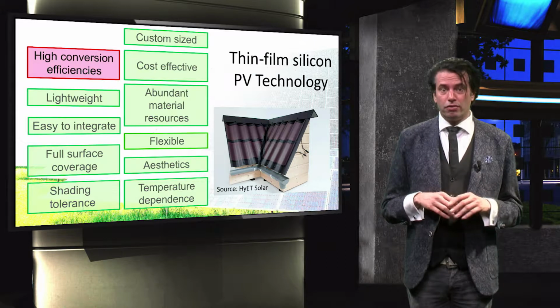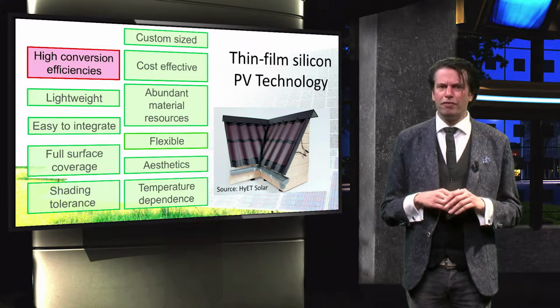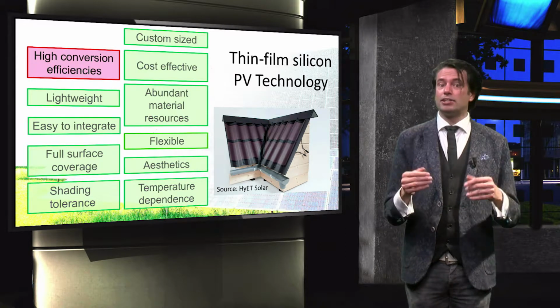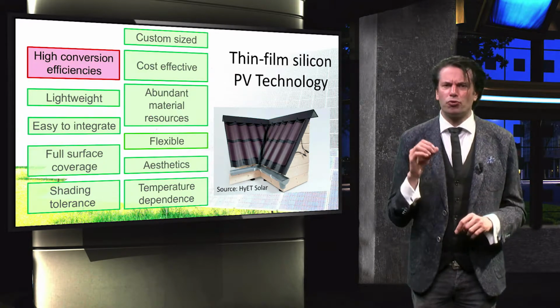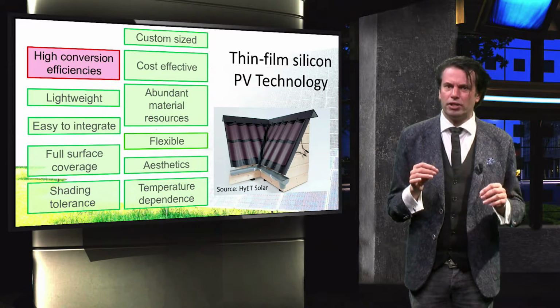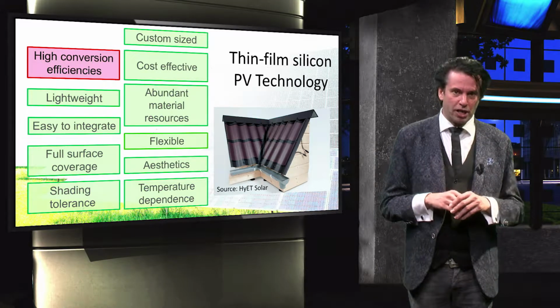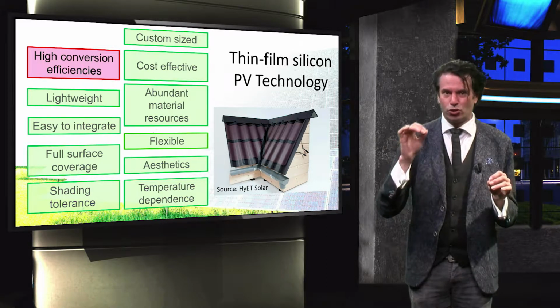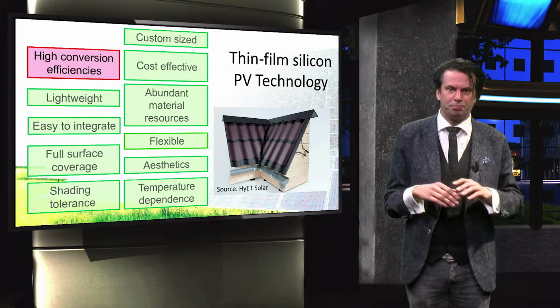For lightweight, flexible modules, thin film silicon is the cost-effective solution. As silicon is resistant against humidity, the requirements for the water barrier in the encapsulation materials are much lower. This allows much cheaper encapsulation approaches, which is usually the component that determines the cost price of flexible modules.